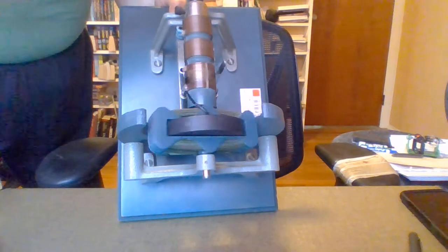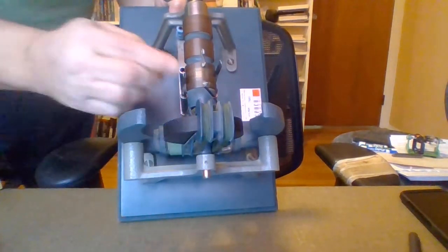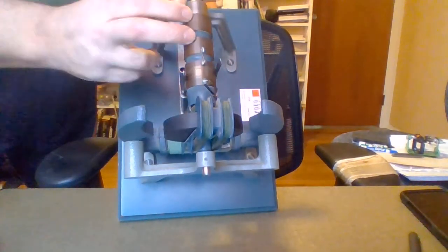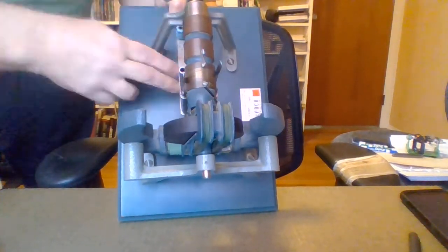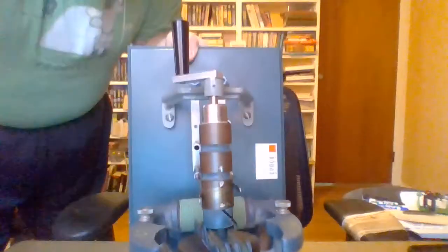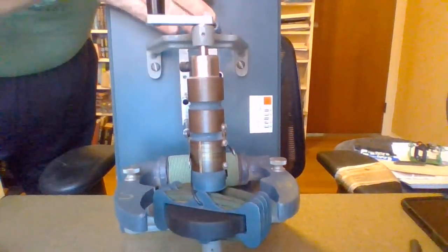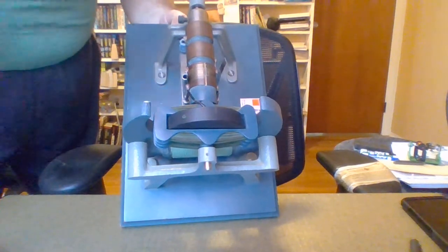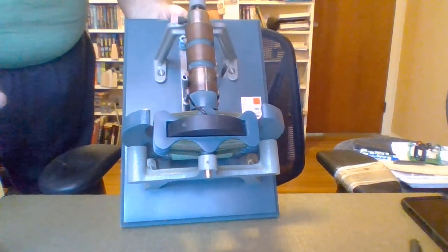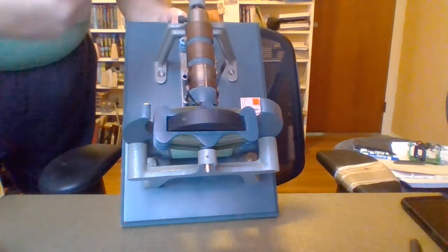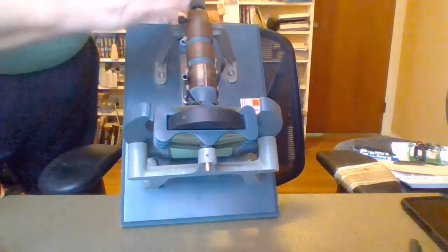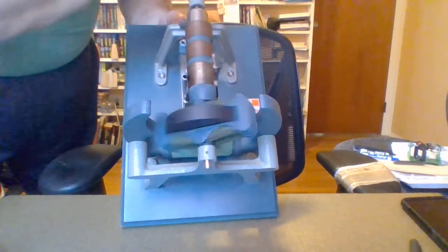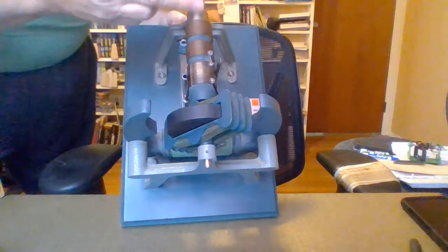So as I would rotate this, it would generate an EMF in the coil, and then because this coil is connected either through the commutators or if I change it to the slip rings, that gets delivered out to the world at large by these other electrodes over here. Okay, and this is the way they do it at Niagara Falls. This is the way they do it at wind turbines. This is the way they do it at steam-powered power plants, whether it's a nuclear power plant or a coal-fired power plant or a gas-fired power plant. The energy of whatever is driving the armature of the generator gets converted into the electricity that then gets delivered out to the world.